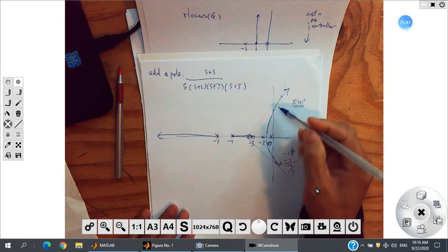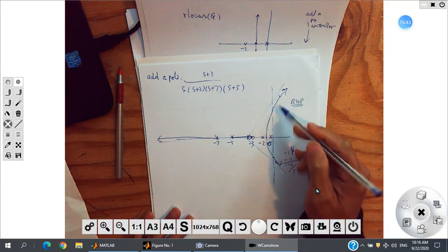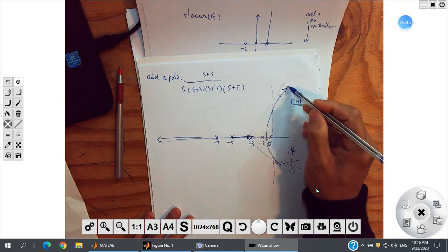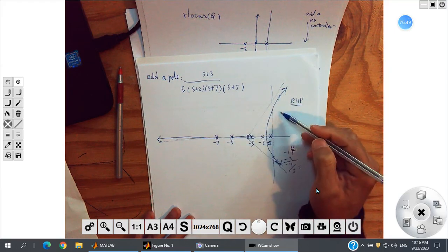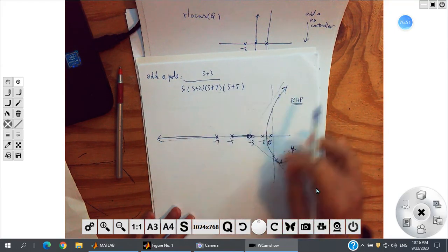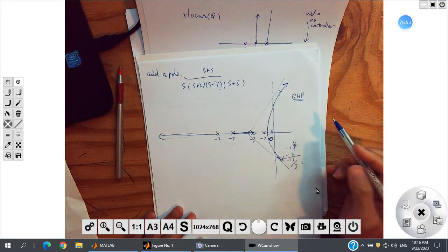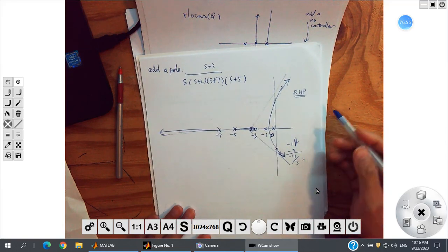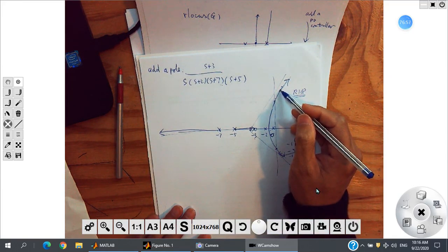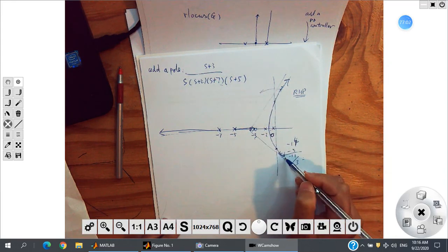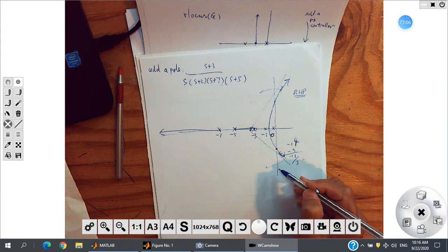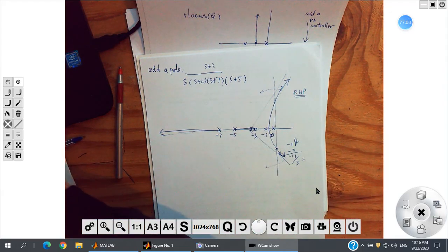But here you have too many poles, so some go to infinity, and for large K this is unstable. If you have a system like this, maybe you want to add some more controllers with some poles and some zeros to move these to the left side. Okay, that's all for today, and see you next time.